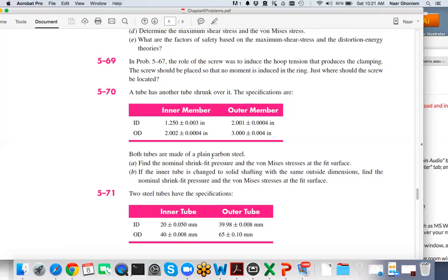So the solution is, let's make the interference very high, because then the interfacial pressure is large, and we can push the assembly to higher and higher RPMs. Well, there's another limitation. If we make the interference very high, there's a potential problem of failure at the interface. That is the chapter we just started to study, and you turn in the homework assignment on failure.